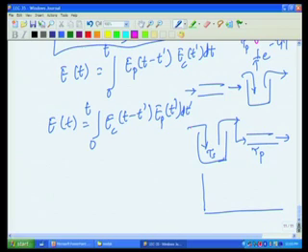Let us now put this pulse here. The moment we put this pulse, we will start seeing the response coming out. For example, if we were to have just this stirred tank reactor, our E c or E at the exit at this point will be 1 over tau s e raised to minus t by tau s, right. Tau s is our residence time. However, what will we see right from the beginning at the exit of the reactor when there is a plug flow reactor in between?